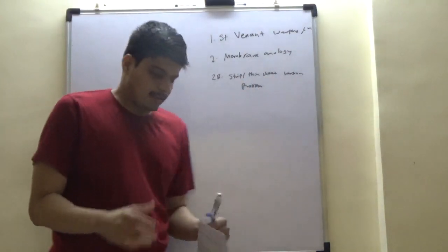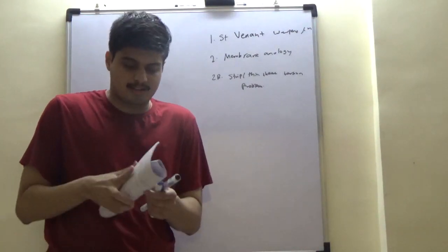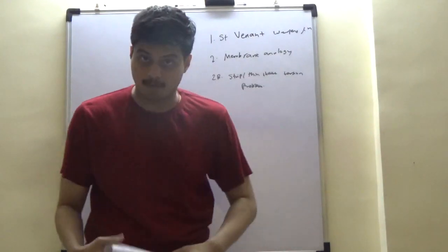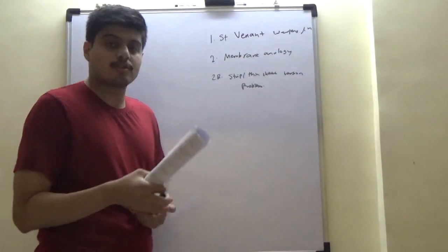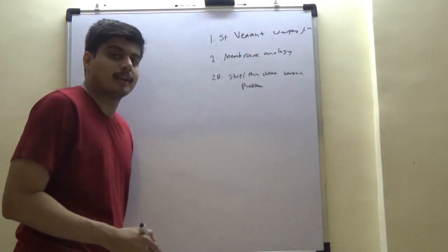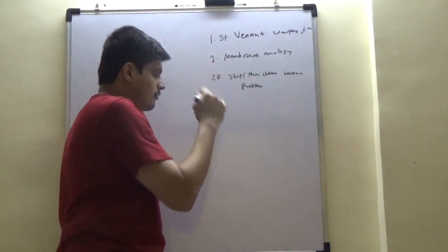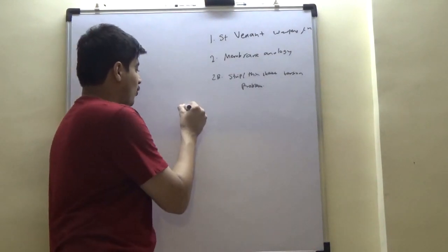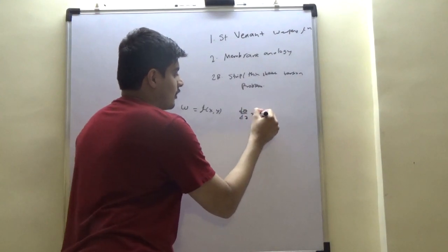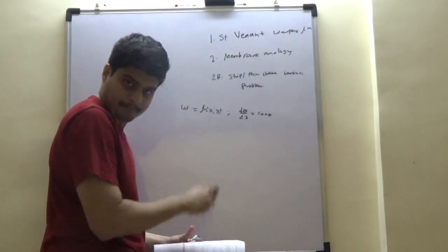Now, the theoretical framework which we discussed in detail was very helpful to understand what happens to a cross section when you twist it with a couple, right? We looked at how the formulations were done, how the theoretical background was formed, how the stress strain behaviors were done. We looked at a square cross section as a particular example, right? Further to this, we always looked at here that warping is a function of xy and d theta by dz is equal to constant, two very peculiar properties of this theory, right?